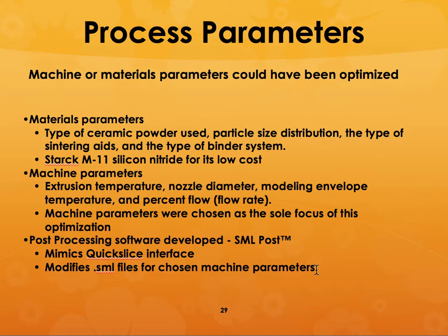So we had to choose that. And the machine parameters were the extrusion temperature, the nozzle diameter, the modeling envelope temperature, and flow rate, and things like that.